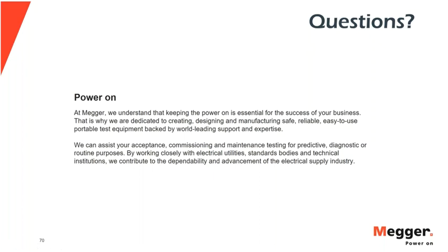There are different things that could be somehow correlated to degree of polymerization of the insulation. And the only problem with the degree of polymerization on a direct testing mode is that you need to take a sample of the paper, and there's no significant sample of paper on your transformer that will give you that exact number of your degree of polymerization. So you can make an estimate. You can look maybe into some external factors like furanic compounds, but that's all it is. It all depends on what the operation is. And what we're trying to do with the diagnostic process is to make a strong statement on what is the health condition of the transformer at this point.